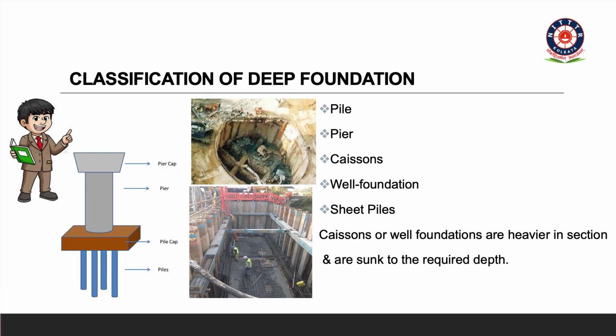See, this is the pile, this is the pile cap, this is the pier and this is the pier cap. This is the well foundation. Well foundations are heavier in section and are sunk to greater depth. This will be done on the seashore or where this type of soil is encountered, and we go for a well foundation.